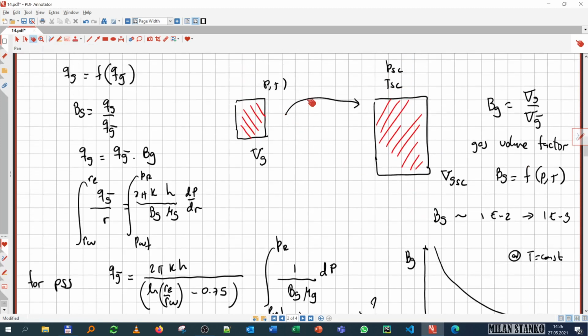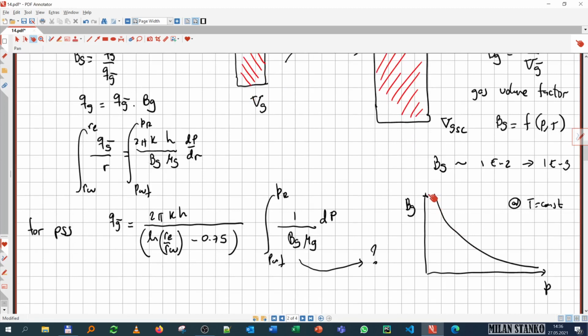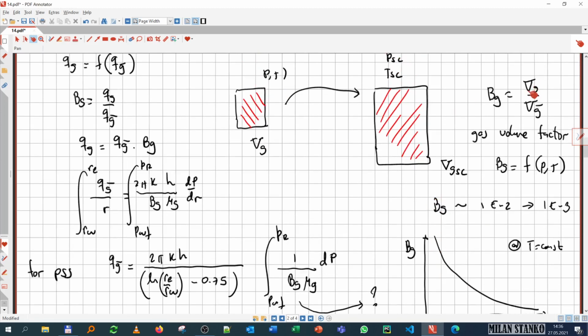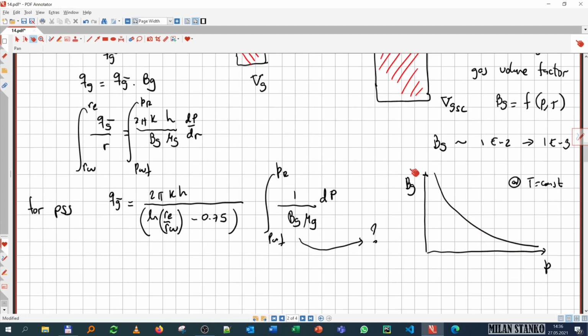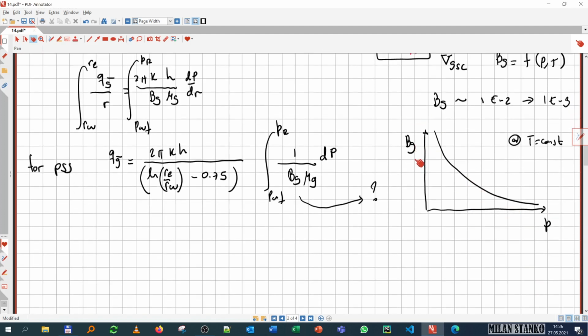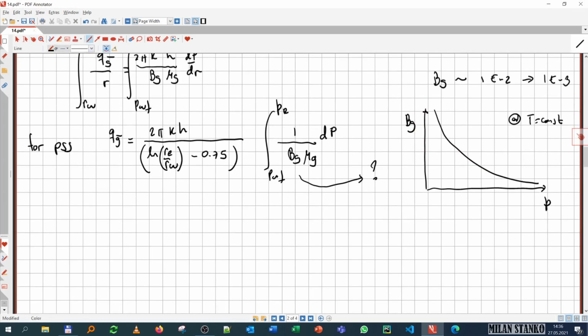And if I come closer to surface pressure, then the ratio is going to be bigger, because the ratio is going to be closer to 1. Essentially it has some behavior like that. And the viscosity of the gas follows a similar trend with pressure. Okay, it has a trend something like that, increasing, going up. Because again, you're putting more molecules one next to the other. There is more friction between them, and it causes more shear when it's flowing.